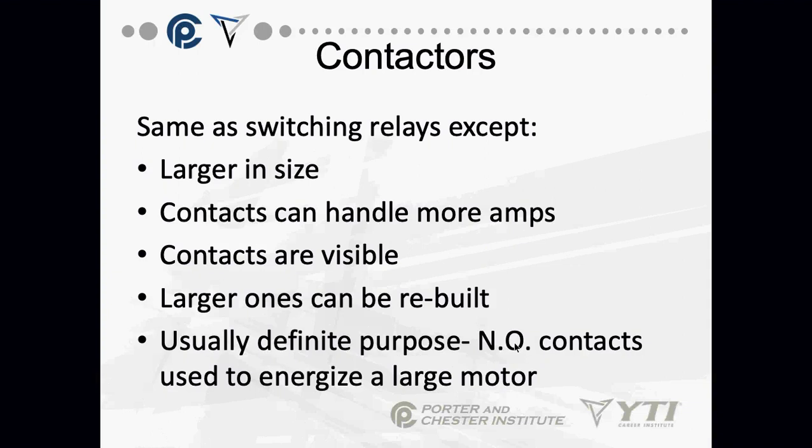Contactors are the same thing, basically. They're the same as the switching relays. They work in the identical way, except they're larger in size and can handle more amperage. The contacts, unlike in the relay, are visible in the contactors. And the larger ones, we can actually change the points and the springs out.